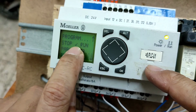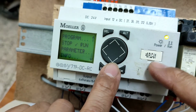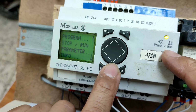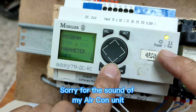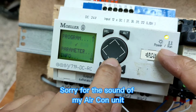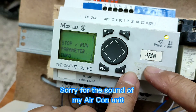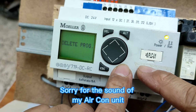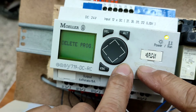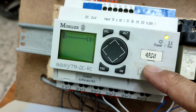As you can see, now the check is on the stop, which means that the PLC is in program mode. Now I will go up so that the program will blink, and press OK to go inside the program. Another press OK. Now I'm inside the PLC program,